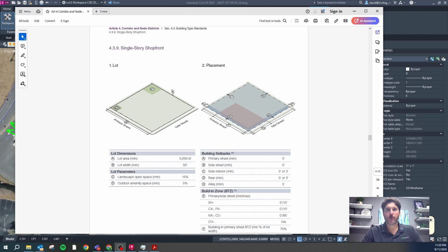A Unified Development Ordinance is an ordinance that combines multiple things together, a lot of times zoning, land use, and subdivision regulations. What I usually think of is that in a UDO, they're more likely to have regulations for different types of projects, and each type of project might have different dimensional requirements, whereas a regular zoning ordinance might just say you're this zoning, your setback is X, and your landscape strip is Y, and that's it. So in Roswell we have a UDO, and they have lots of different types of land use and different dimensional requirements for it.